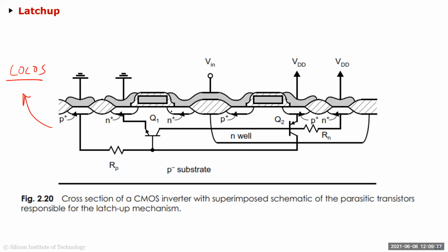Okay. So here, if you see, this is an NMOS, obviously. So this is, let's say, your source, drain of your NMOS, and the source, drain of your PMOS here. This is your NMOS gate, and your PMOS here. Now, what's drawn here is to show you that there is an NPN structure, which is parasitic to this NMOS and PMOS sitting right beside each other.